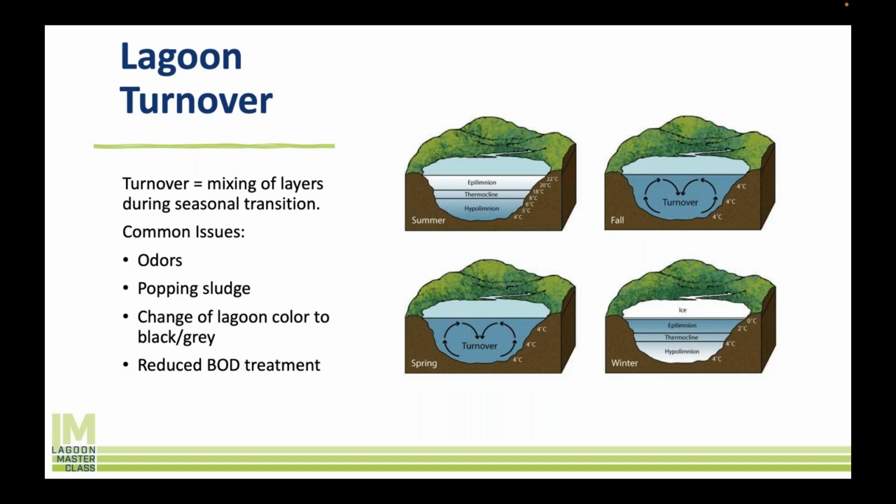Now, turnover. This is an apropos topic because we're sitting here in the spring, and I've had a number of calls about this already this year. Often lagoons are referred to as ponds, and they look like ponds in a way. They're actually a wastewater treatment facility that looks like a pond, but they do behave like ponds in a lot of cases, especially if you have a facultative lagoon, i.e. no aeration in it, or a partial mix aerated lagoon, i.e. it's only partially mixed, which is, say, between those two, the vast majority of lagoon systems.